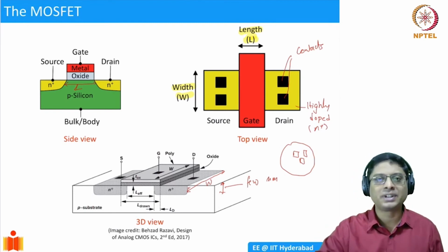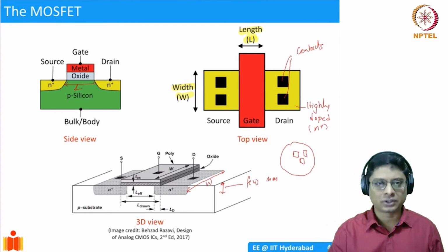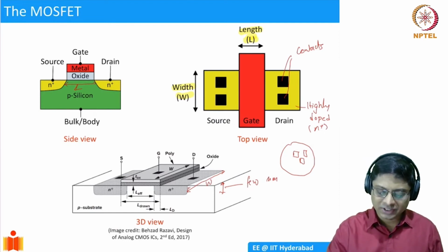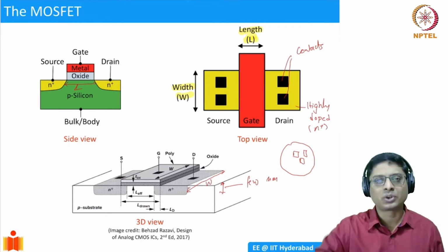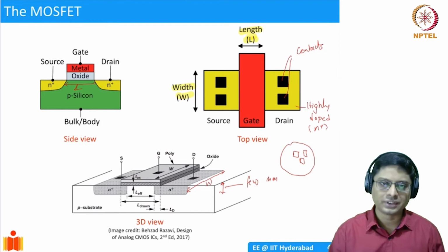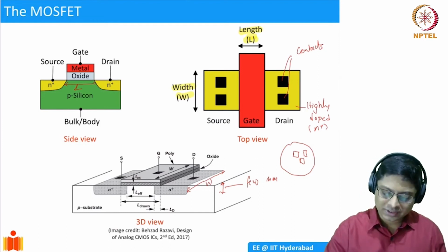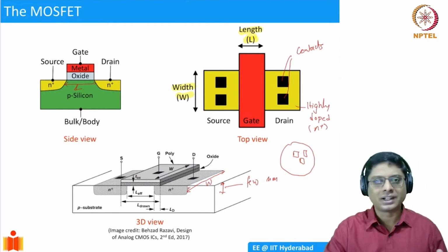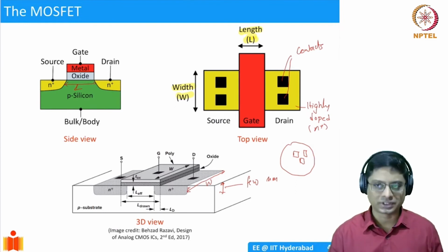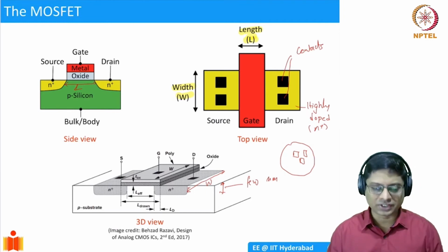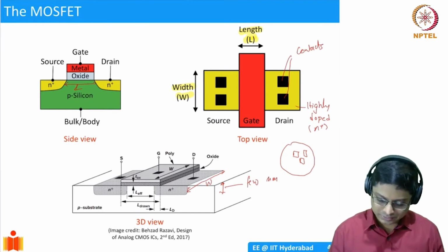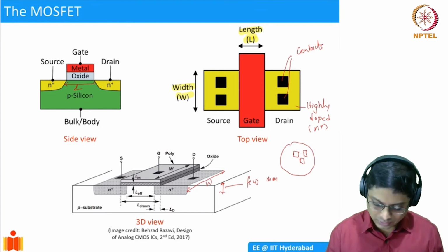If we directly put a piece of metal, it will have a contact resistance. We mentioned this already. So now to avoid that, we can engineer these contacts in such a way that, I mean, one contact would suffice, but we just typically make more contacts to minimize the contact resistance. Okay. And these things I can connect. So this will be connected to a metal, another metal piece, and then so on. Okay. So that's how the transistors work. So this is a physical structure, but how does it operate?